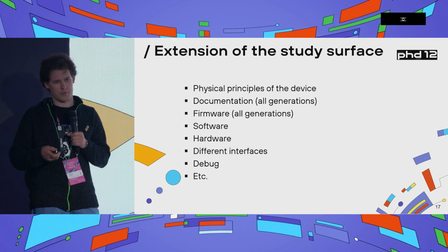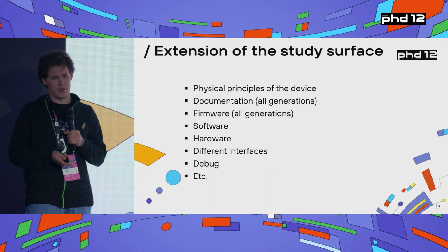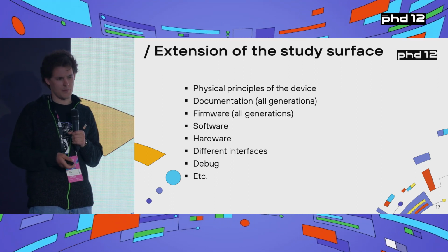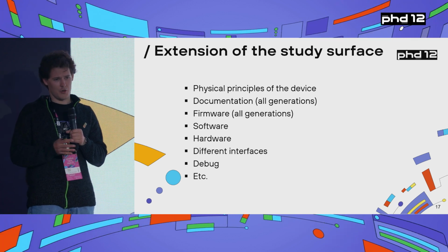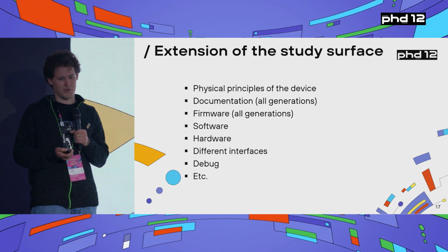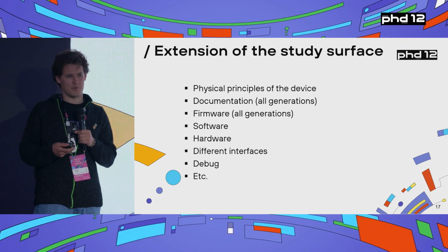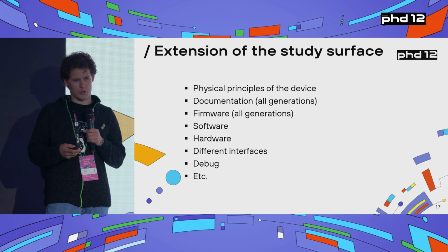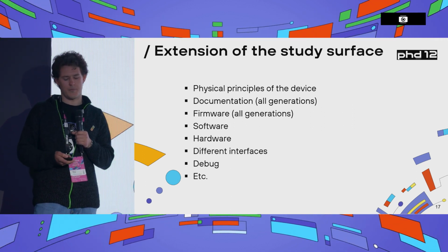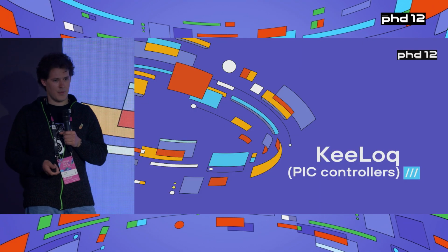So you need to learn interfaces, even simple ones like UART, which does some very simplistic checks. Now I state debug here in my slide. In most cases, that's JTAG, and it has very complicated and very long specs. Interacting with these interfaces can be very difficult. In most cases, you cannot really rely on the standard issue utility for debugging.